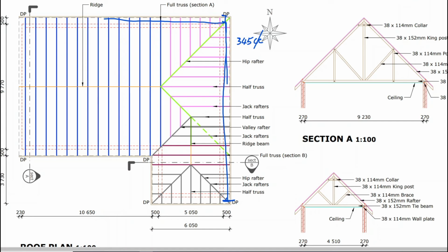And since this length runs with the slope and not up the slope, our deduction must be on plan dimension because we're looking straight down. We're going to have to reverse engineer 345 to be 345 divided by 1 over cos 28. That is the one scenario I've seen where it goes backwards.